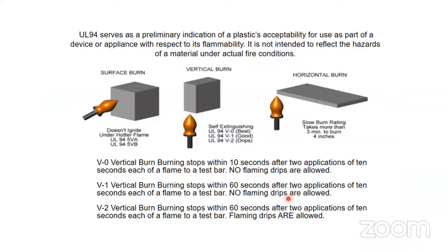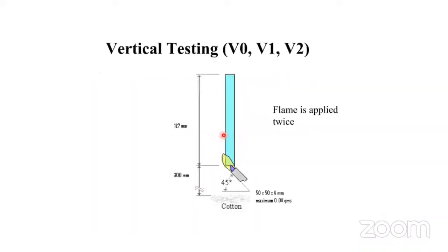So again, depending on the applications, there are different types of flame test. Like we have studied vertical burning for polymeric samples or hard samples. If you are having a sheet, then we can use horizontal burning as well. Or if you are having some blocks like paint blocks, then for that we can use a surface burning test.